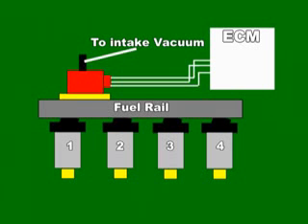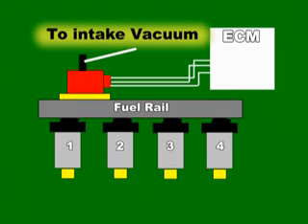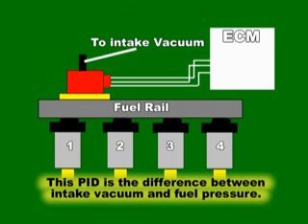In some fuel rail pressure sensor applications, the sensor is also connected to the intake manifold vacuum side. In this arrangement, the sensor's signal output is a differential signal of fuel pressure to intake manifold, which the ECM uses to control the fuel pump speed, therefore maintaining the fuel in the rail in liquid state and preventing fuel vapors. The differential signal of the FRP sensor takes into consideration the amount of intake manifold vacuum of the engine. This way the ECM can properly control the actual amount of fuel leaving the injectors.